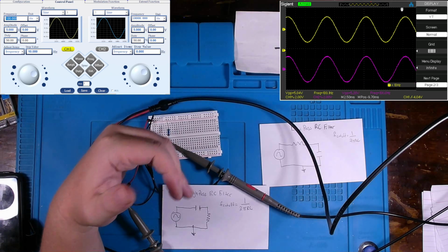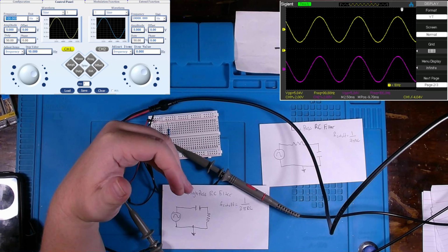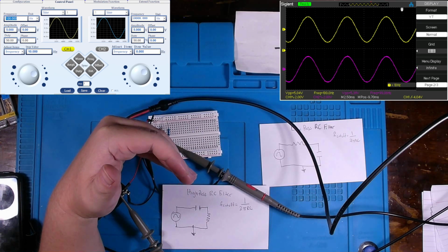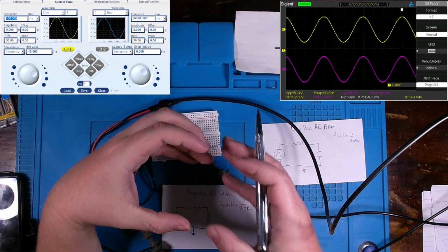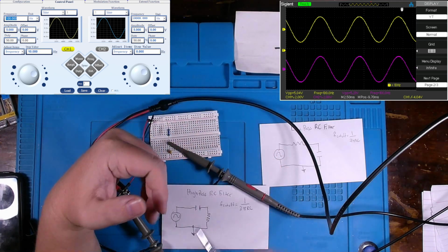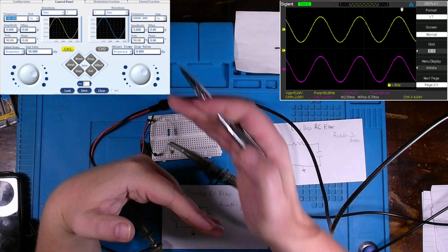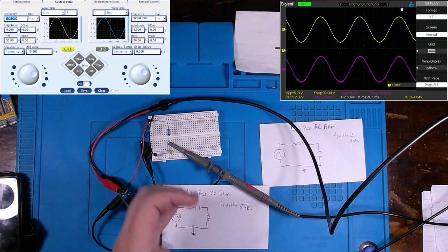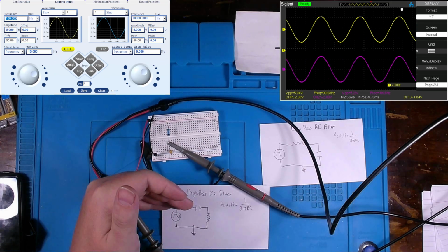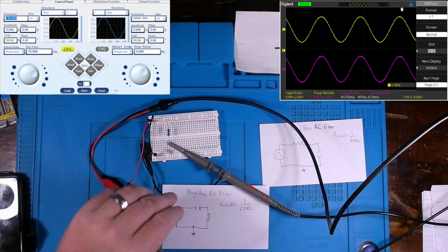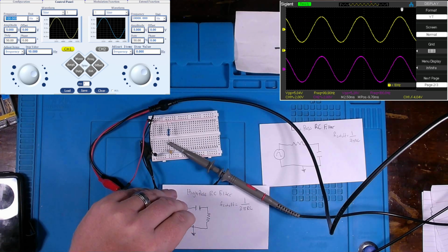But if I was to establish a high pass filter, I could essentially eliminate that hum at the speaker if I was to tap off of it and create myself a little box to hook up to, and use my oscope beyond that filter I established. Obviously, the capacitor at the filter is going to have to be rated at almost double whatever voltage rating is coming to the speaker.